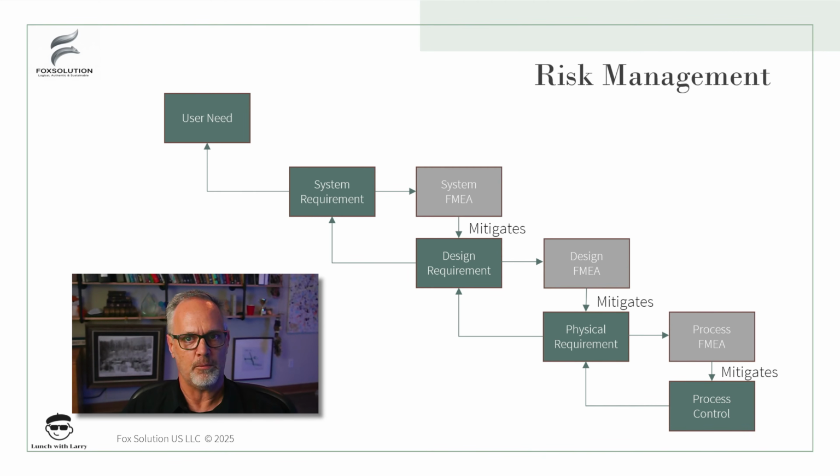And then finally, the process failure analysis takes those physical requirements, like the 3/8 inch bag seal, and then defines all the ways that that bag seal wouldn't be delivered. So you get a hair in the seal, which creates a tunnel, or we have delamination of the bag. Those different problems are associated with the manufacturing process, cleanliness of the process, or maybe how the sealing's done, the pressure of the seal, temperature of the seal. And then what ends up happening is we have a set of process controls that are necessary to assure that we get that 3/8 inch bag seal.